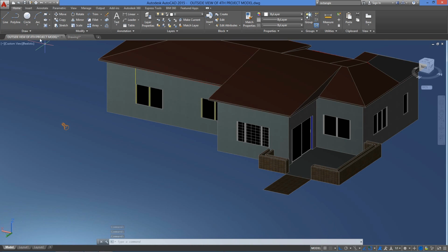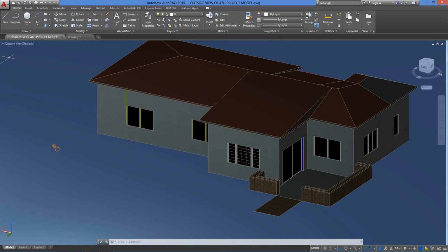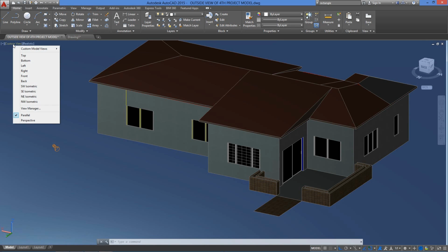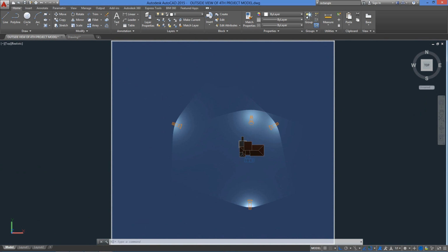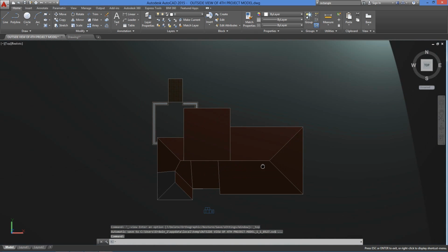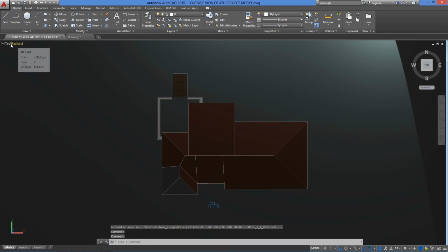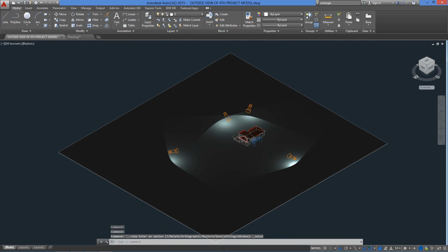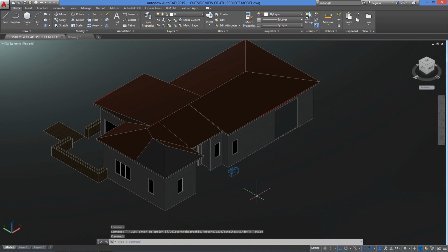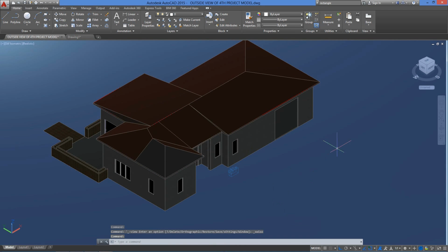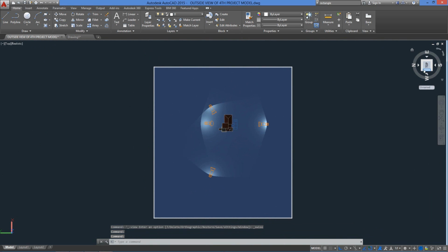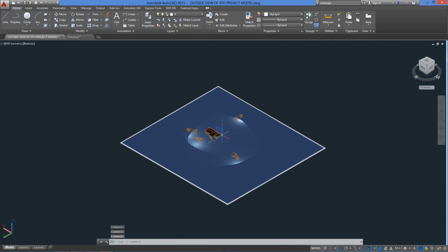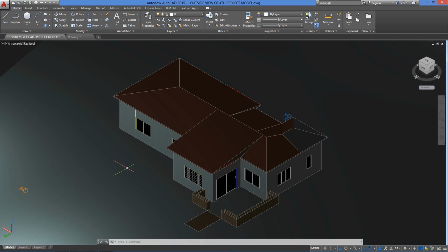Now on the top left hand corner of the model space, we have a couple of buttons that are mostly used in 3D. The view control, for example, is used to select the drawing view we prefer. Like now we can change from plan view to an isometric view. The same result can be obtained with the steering wheel on the right. By clicking it, we can select and change the predefined drawing view as well.